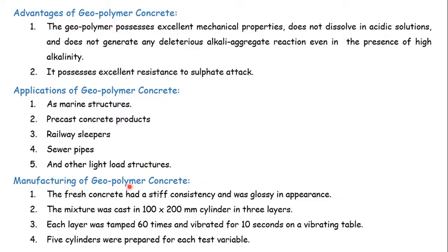The manufacturing of geopolymer concrete. The fresh concrete has a stiff consistency and a glossy appearance. Due to the polymers present in the concrete, there is a glossy appearance, and the stiff, harsh consistency is because the polymers absorb some of the water present in the concrete.